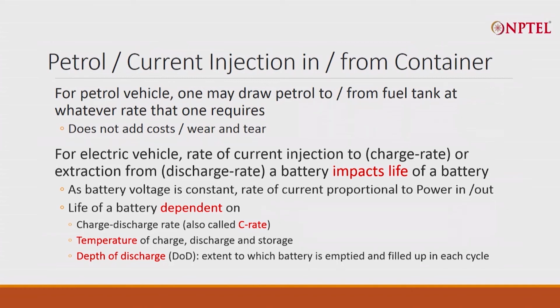Batteries you should charge slow. You should draw out currents slow. Charge rate, discharge rate needs to be slow. If you don't do it, you can do it, but then the life gets further reduced, which means again you have to pay. So, charge discharge rate impacts life of battery. Complicated, not so in a fuel tank.